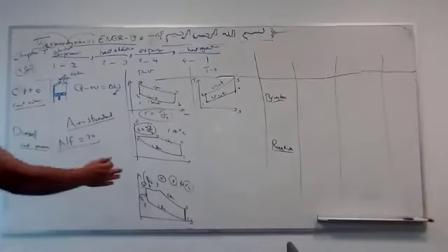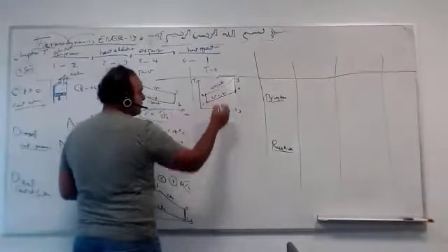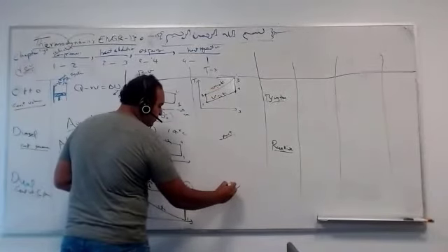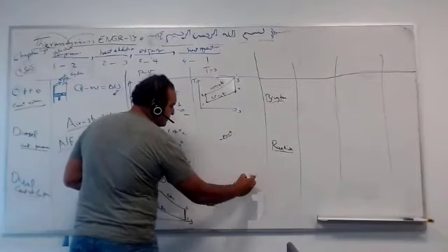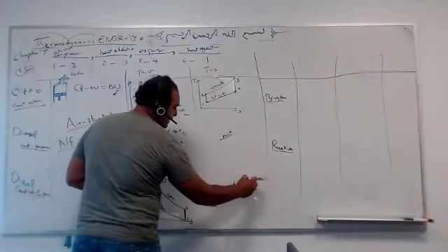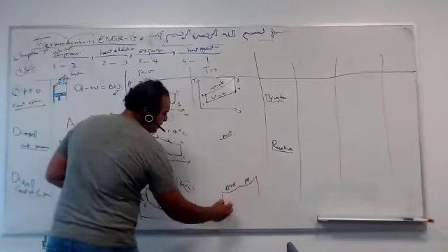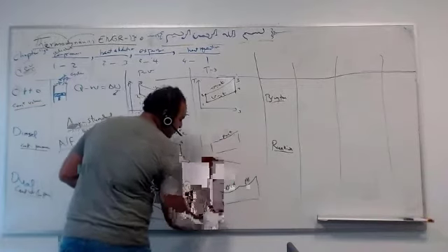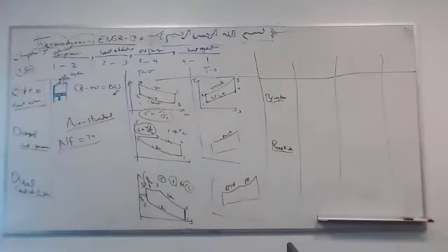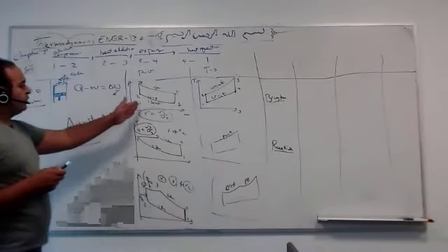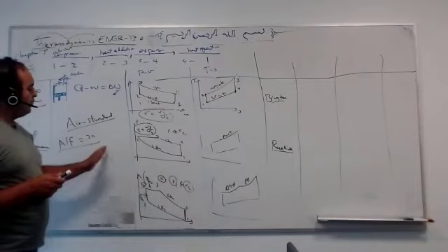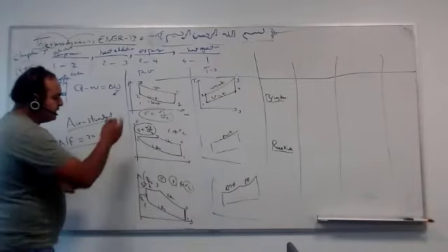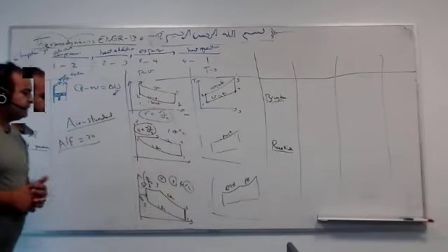And the same for this one. Everything is the same, except this is pressure constant. Here, some volume constant first, then pressure constant. Okay, these are the 3 cycles. Does it make sense, guys, for you? And we can predict the thermal efficiency, which is 1 minus 1 over R to the K minus 1. The one here is complicated with R and RC, including K. We need K, of course. And the same for this one.